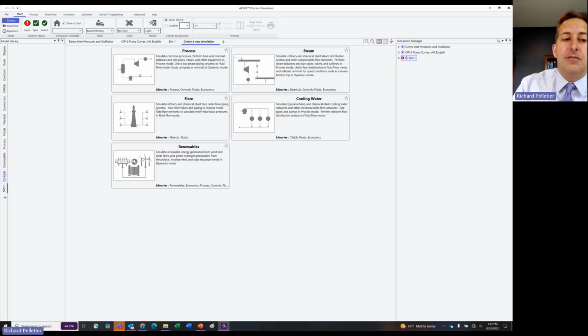just like you would the simulation model library. The difference between the two is that this will be accessible by all of your simulations on your install. So every one of your simulation files will be able to access your custom library and get your customizations. However, they're not stored in the SimX. So when you export to a SimX, that information is not stored in there. The reference to this library is noted, but the actual models themselves are not stored, right? Whereas the simulation specific model library stores all of these custom models in the SimX file itself. So when you create the SimX, that's the only file you need in order to replicate everything in your simulation.